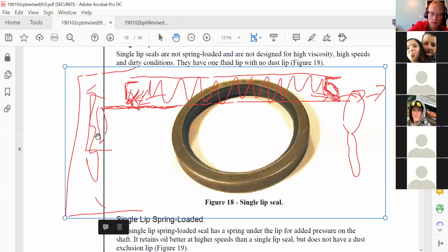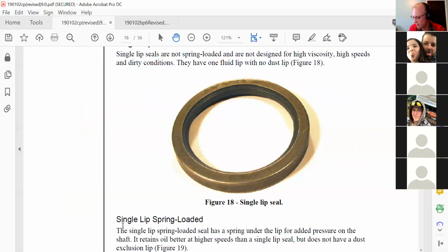So it doesn't go in your drum. Yeah, so you know when you're greasing. Yep. Now, with that being explained, these single lip seals only seal in one direction. If pressure is applied from the opposite direction, they have no resistance and they let it right out. Okay. Does that make sense?